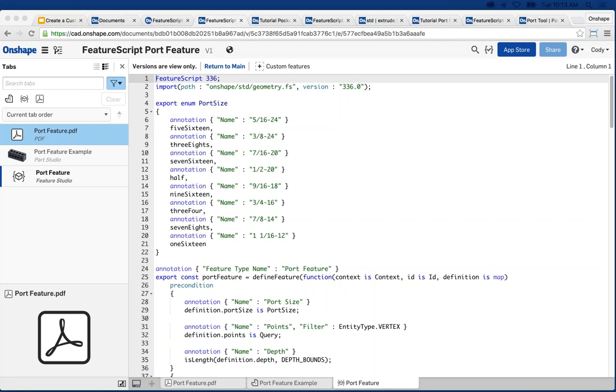Another example I always like to point out is that I personally have created what we call a spline feature for straight splines on a shaft. It will detect the direction face, so I don't need to select any normal directions. It will detect the diameter of the shaft and then apply the appropriate dimensions based on the diameter of the shaft, so you can do all this logic that makes it impossible to create incorrect features and makes it very easy to apply them. All kinds of neat things that you can do. And I'm going to get into a simple example of it in just a bit.